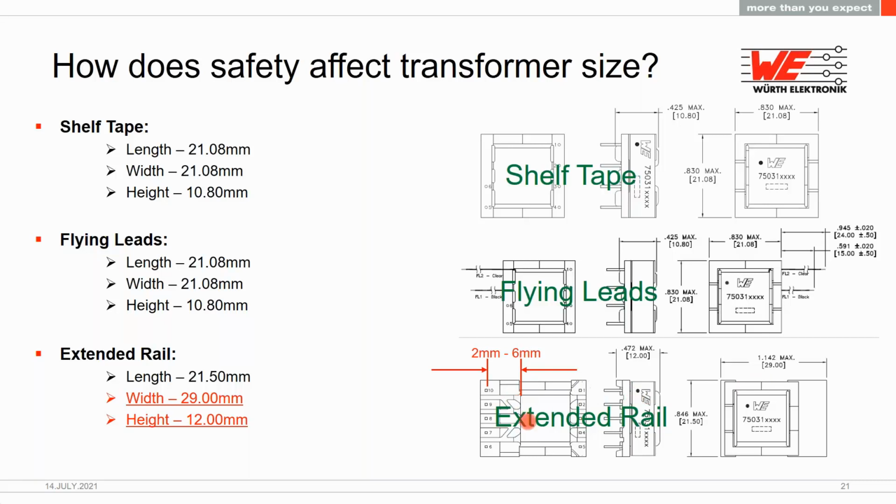I show a through-hole concept here, but keep in mind with a surface mount design, this would also be very critical. If the depth of this slot where the insulated wire would lie is not deep enough, there's potential that the insulated wire would rest on the PCB directly, and your pins of the transformer would now float off the PCB during the reflow process.